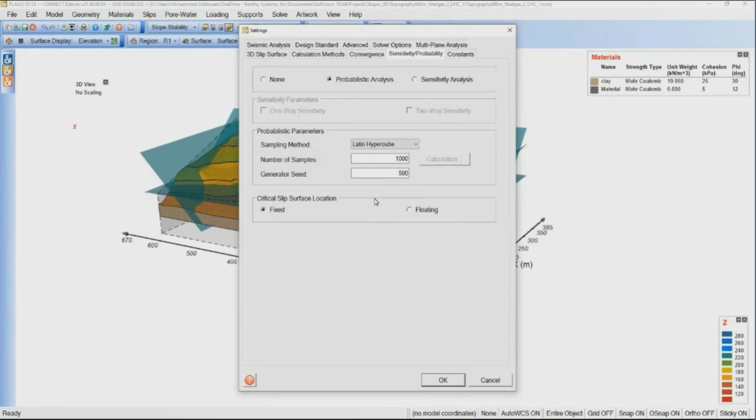So this takes really short time for the sample parameter generation, and we can get the same result as Monte Carlo with a smaller number of samples. But anyway, here we are using the fixed number of iterations as Monte Carlo, 1000. That means Latin hypercube will give a better result than Monte Carlo with the same number of samples.